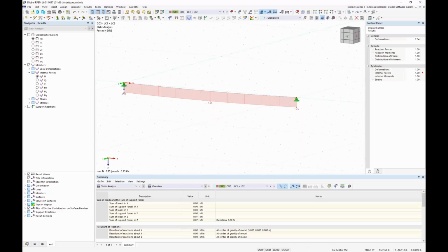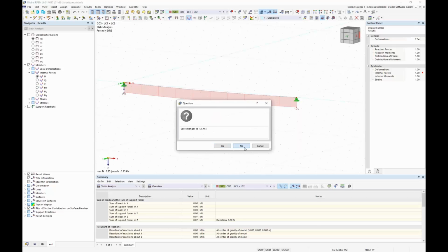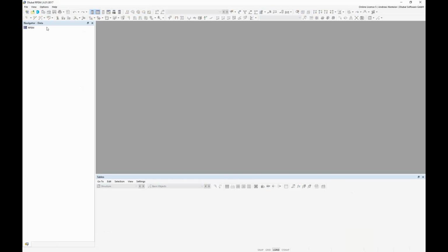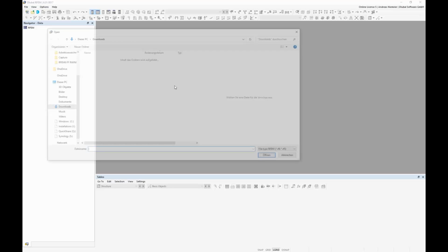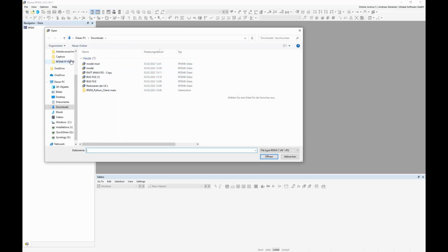Of course this is a special example because the shape for cables always depends on the form finding condition, so how big is the sag, for example, plus any load for which we have to detect the shape, the self-weight, for example. But there exist different examples. Maybe the next is here,